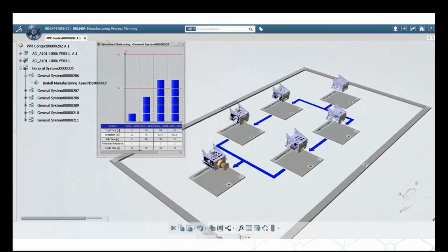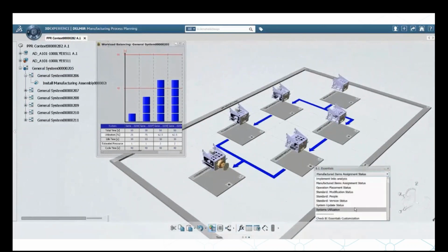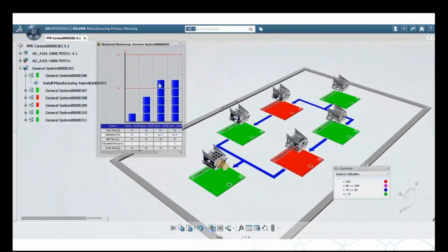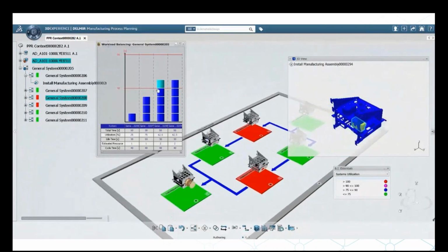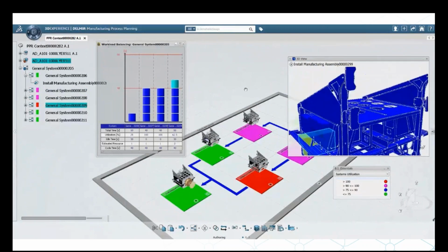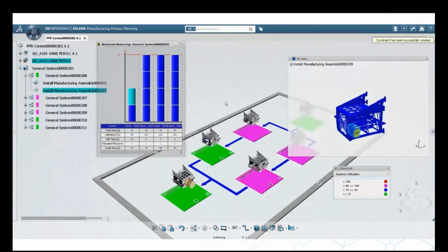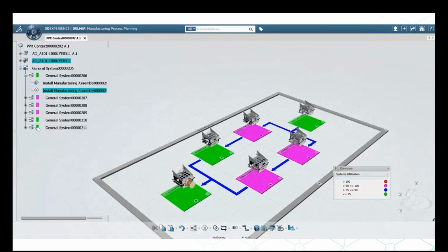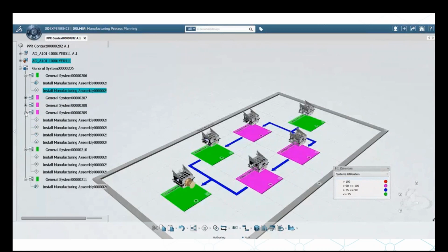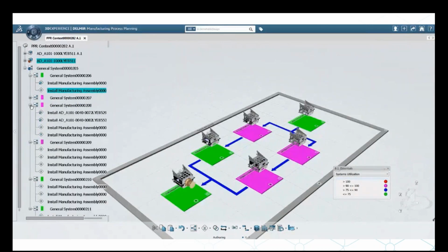That means we'll be able to see how much time is going to be consumed for every work instruction or every work cell, and can you see that the system is telling me which one is above the capacity limit. So in that case, what we can do is line balancing. That means the system will allow me to change the sequence of the individual operations at that particular workstation, so that no particular work instruction takes longer and all of them are equally distributed. So every workstation's capacity is something we can manage.